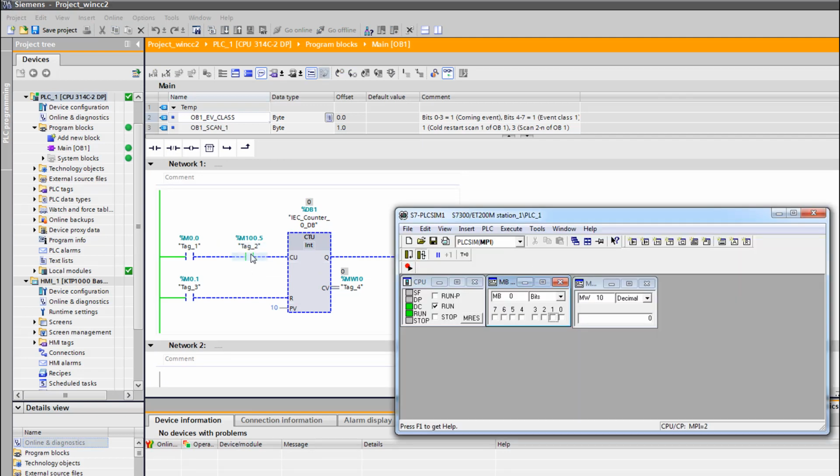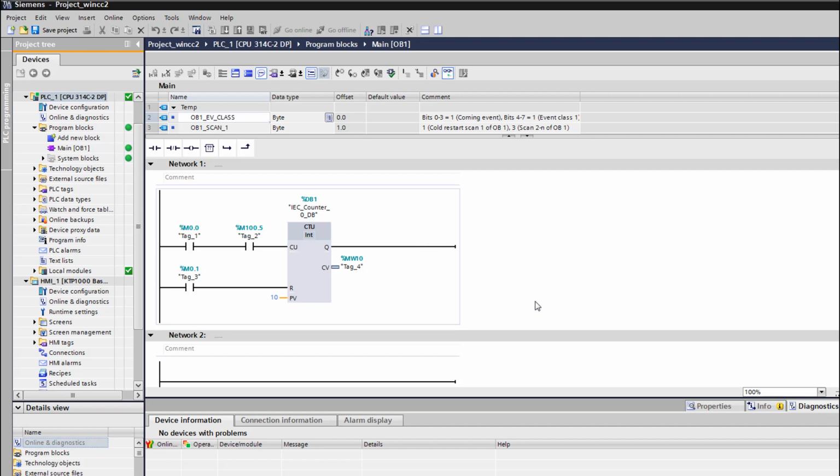So you see how this clock signal generates a pulse every 1 second. We'll activate our counter. Now it's incrementing. This is the value. I can reset it. If this reset is active, it will not count. Okay, so this is our counter. It's very basic and very simple.